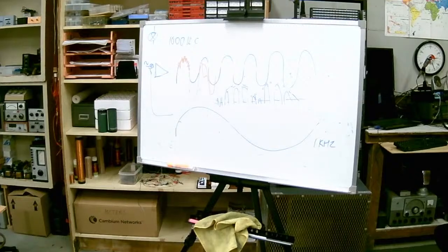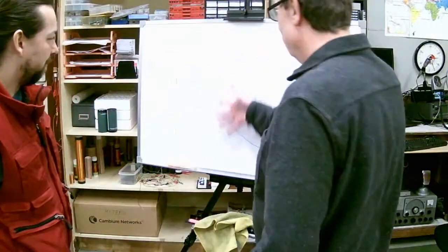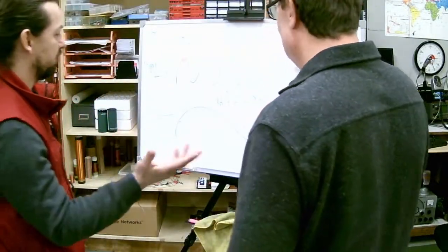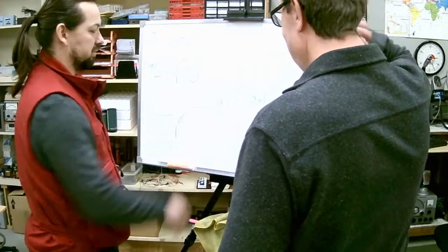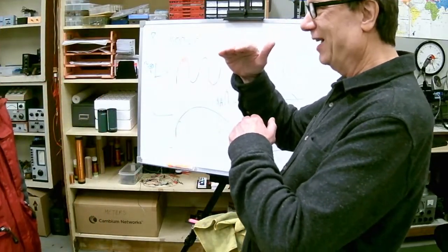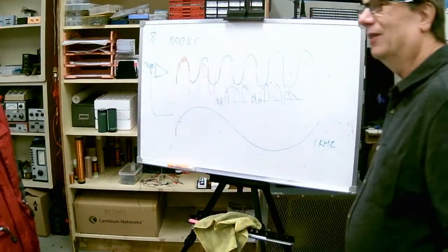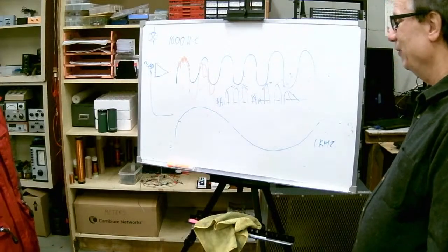This right here is just pulling out this part right here. So we're seeing both sides. Now, the reason you need detectors is because it goes up and goes down at the same time, so it's going to cancel everything out as far as the envelope. So you drop off the bottom half, and then you can put it back through the envelope detector.